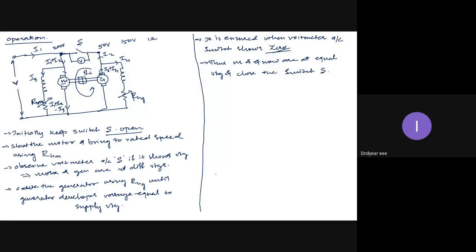but I close the switch. What will be its effect? It will not physically damage the machines. It will damage the performance. Okay. So how much can I load the machines? Up to its rated current, right? Always we have seen the machine should be always loaded up to their rated currents.